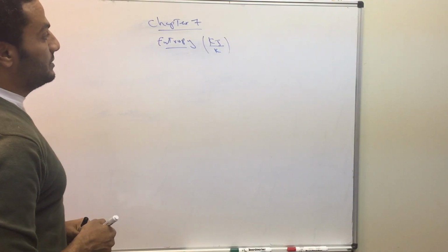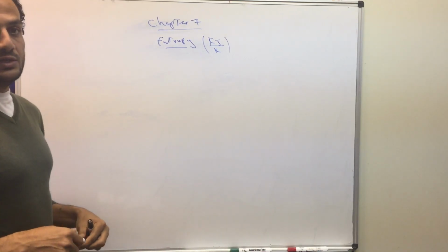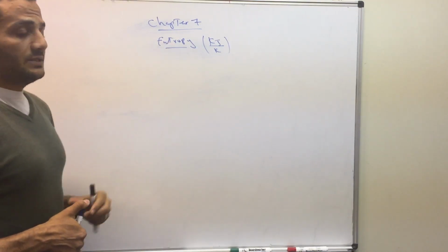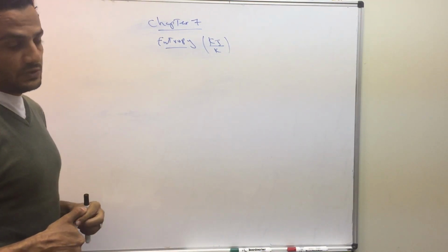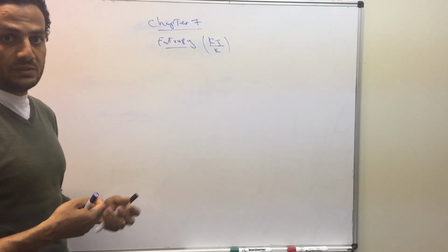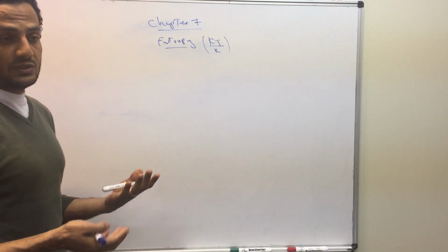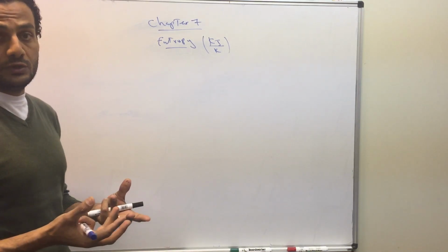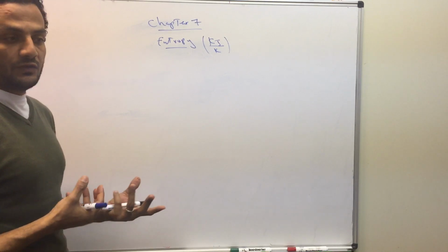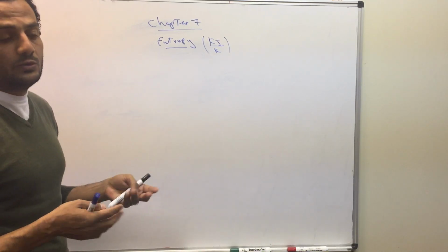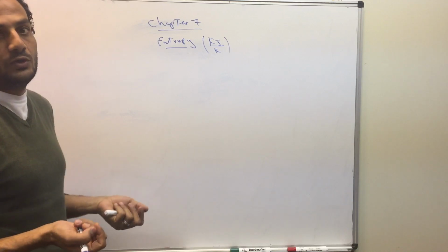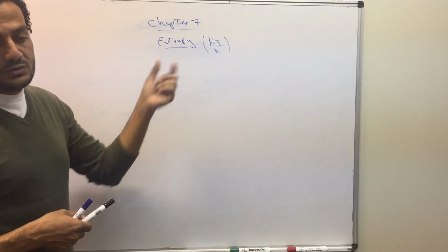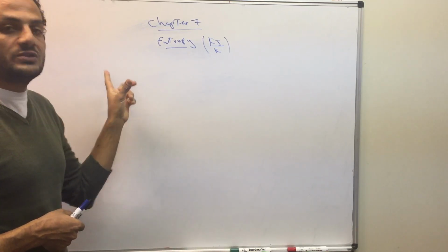Also, we have another term which is called the entropy generation, which is the amount of entropy that is generated within the system due to the losses within the system. So any energy loss within the system, let's say heat losses, the friction losses will be converted to heat, but we cannot convert this heat to work. The heat generated due to the friction losses will be absorbed by the molecules and used in the molecular activities of the molecules. So we cannot benefit from this heat transfer. That's why the entropy generated within the system gives us an indication about the losses within the system.